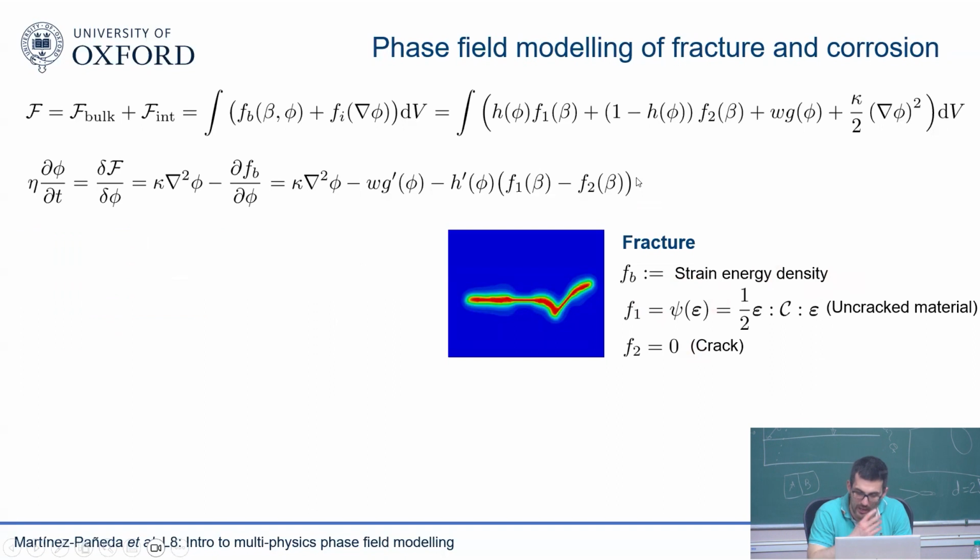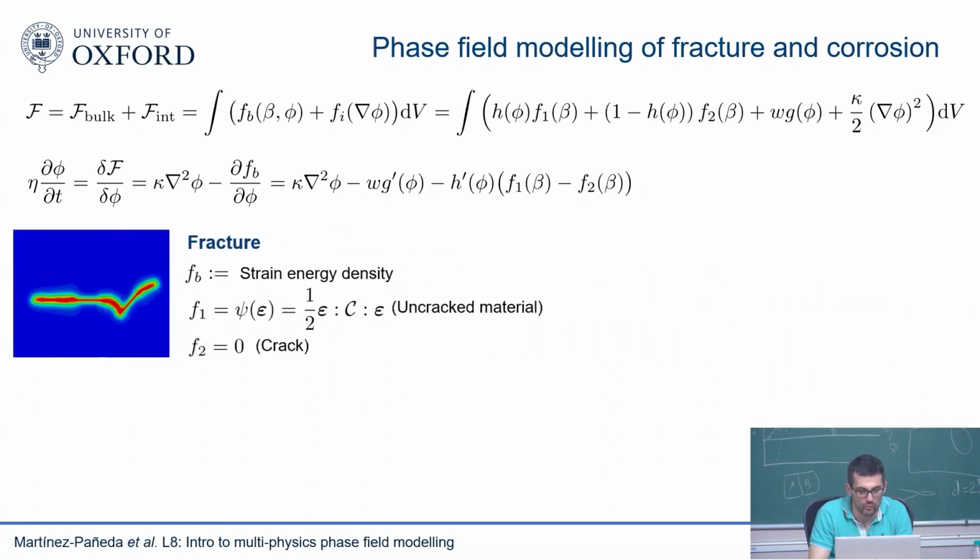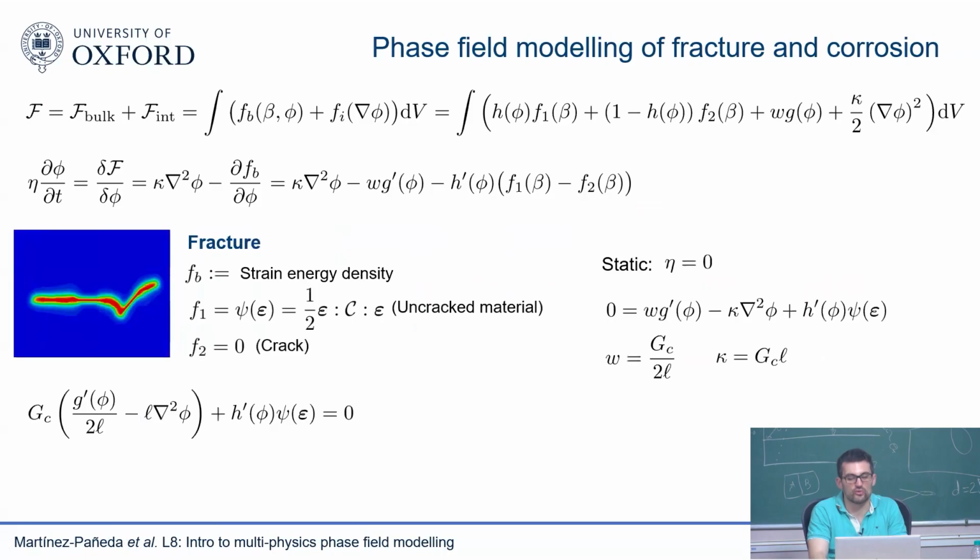That's the idea. And when you do that, let me focus on the fracture case. The other thing that you need to consider is that we deal with a static problem. So normally in fracture, as I told you the other day, you could have this term if you want to get some extra convergence properties. But if you don't care about convergence, normally most people will just say this guy is 0, fracture is a static process. I mean, it can be a rate-dependent process if you have other rate-dependent phenomena. For example, you can have material rate dependency. If you have an impact dynamic, your fracture will be different, but it will be different because the constitutive behavior of the material is rate-dependent, not because the fracture process itself is rate-dependent, or any other rate-dependent phenomena like hydrogen.